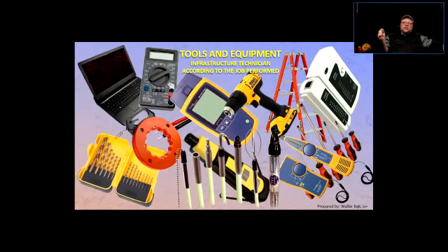If there's a little bit too much untwist, and it doesn't take much for the Cat6 to reject the certification. All right, so the twist has to be done right to the punch. And then we're explaining it to you. Don't damage those wires. Don't step on them, because if you step on the wires, you're damaging the structure of that. And if you damage the structure, you lose the twist in that place where you stepped. And then even if you massage it into place, Cat 6 is not going to forgive you that.